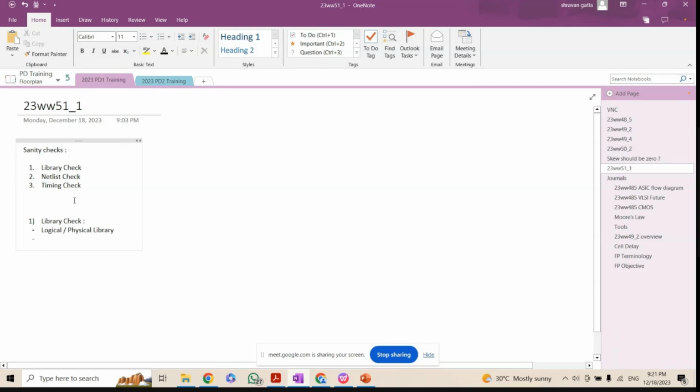Let's say you give the input as 0 here, and you get 1. And if you give the input as 1 here, you get 0 here. It's an inverter, right? So it will invert the logic. So this buffer will be in a confusion mode, like what input it should take. It is getting two inputs, right? So it doesn't know what the correct input to this buffer is. This is the multi-driven net. So two nets are driving this buffer.